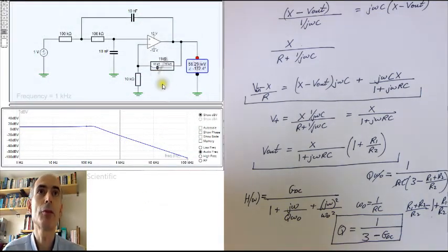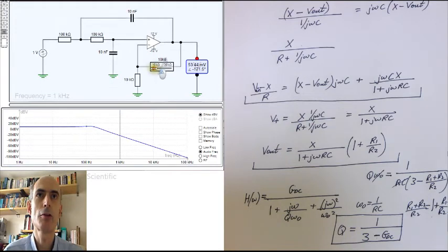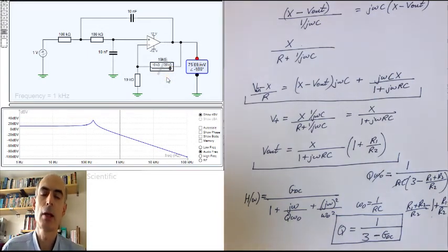We can see it in the simulator here. I can change the gain, and you can see that the gain at low frequencies is changing, because the low frequency gain here is creeping up slightly, but the amount of resonant peaking you're getting around the resonant frequency is also changing, and we're getting a response characteristic of quite a high Q second order system without any inductors.